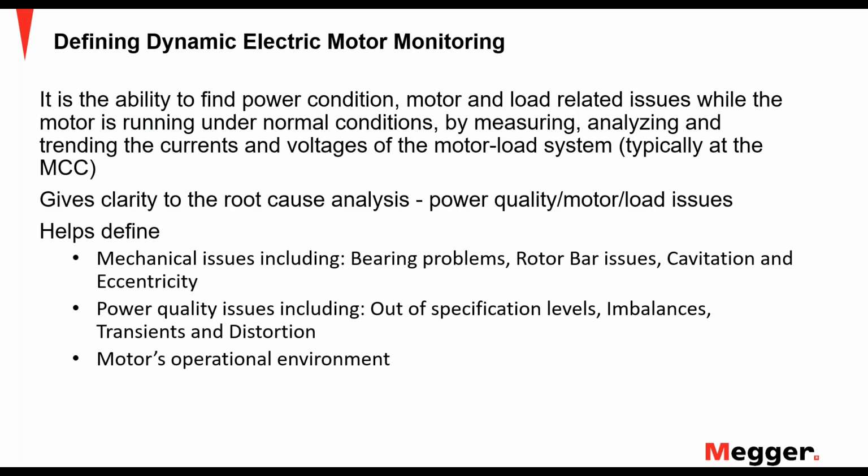So here's the definition. It is the ability to find power conditions, motor, and load-related issues while the motor is running under normal conditions, by measuring, analyzing, and trending the currents and voltages of the motor load system. Typically we do this at the switchgear or the MCC.